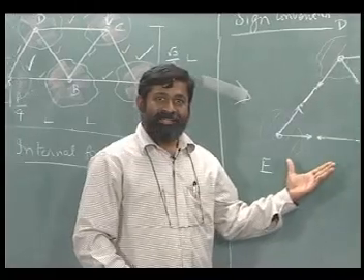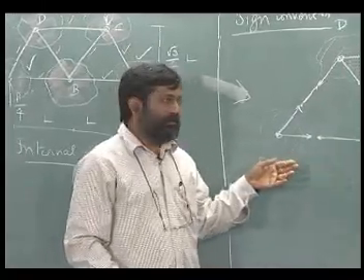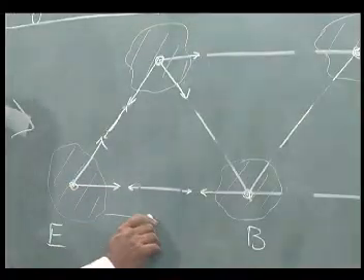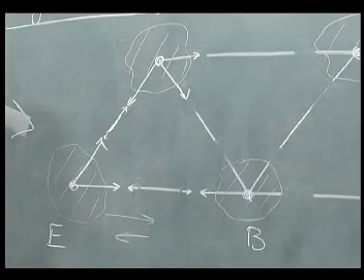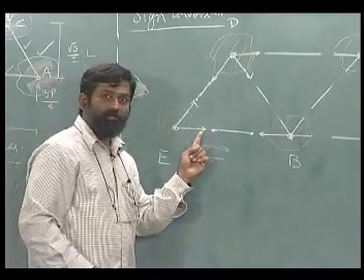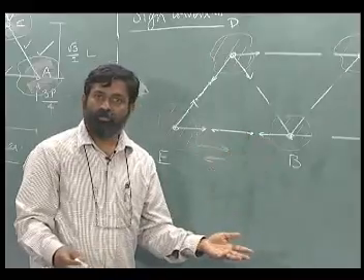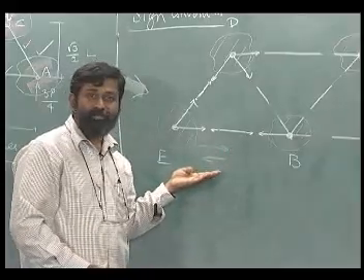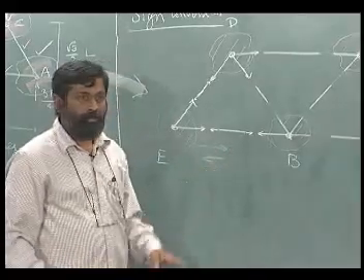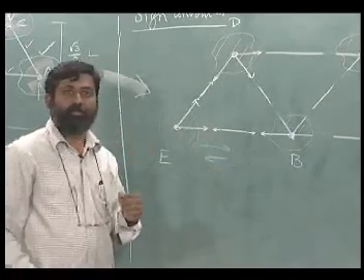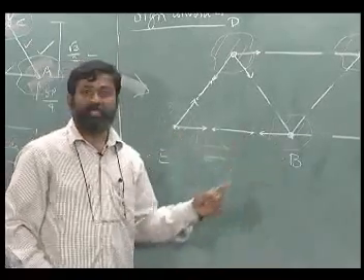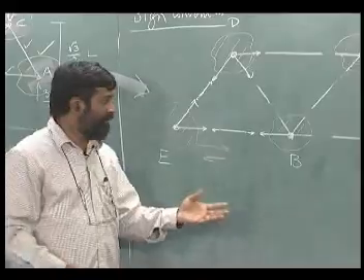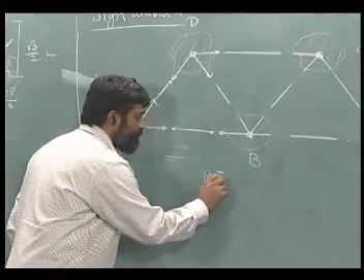Now, at this stage I will have a doubt which direction should I take as positive, this direction or this direction. Is this positive or is this positive for this particular internal force? Now this force, this force, this force, this force, all these forces indicate internal force in this particular member, and therefore this confusion is a very common confusion. In order to understand this, the first thing that you have to remember is the entire member BE is having a single internal force. Let us say BE in this particular case.